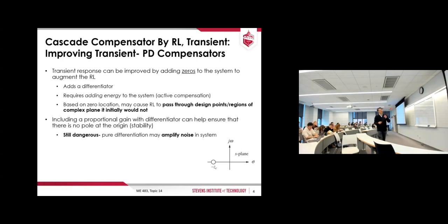Now, the major difference is, last time for designing the PI controller as well as the lag controller, we had this design point established through the proportional gain K. We set the design point based on the zeta value, and therefore we had this line.